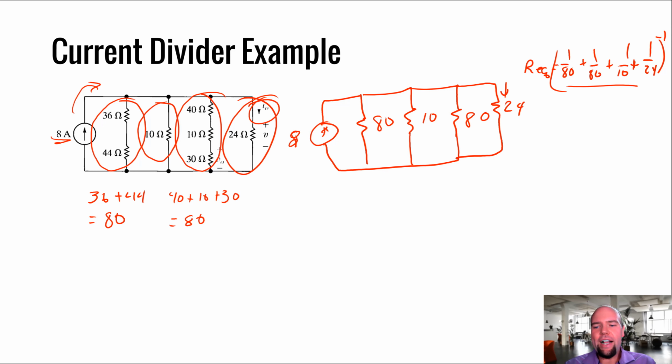And what that means for analysis is, yeah, you can switch the order of things in series or in parallel and it doesn't change the equivalency of those things. Sometimes there's a specific configuration you're trying to analyze and therefore you have to keep it in that configuration. But for the equivalency of the math, for equivalent resistance, it doesn't matter. And that makes sense if you think about this circuit as actual branches of resistors physically floating in air.